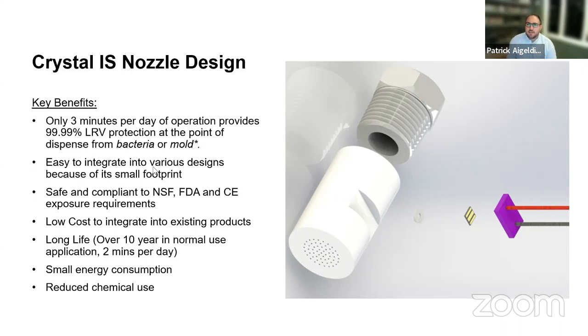UVC LEDs can be used off grid at relatively low cost for developing areas or areas that have water quality risks. The issue in those markets is that many times you also need microbial treatment on the incoming water supply. Depending on the flow rate, that cost component is what we're trying to drive down through some of these field and nonprofit efforts. Short answer, yes. Longer answer, we need to commercialize the design with some volume.